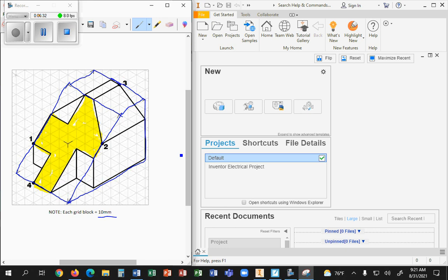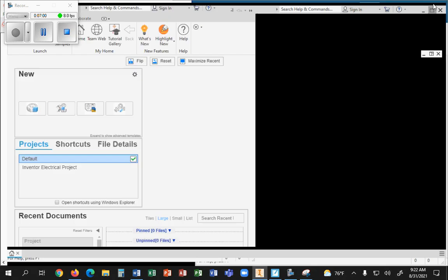And now moving over to Inventor. Okay? We needed to know the units of measurement. We know we're going to do the first angle projection because it's metric, but the first angle projection doesn't kick in until we're in detailed drawings. Remember that. So we're going to go to New. The first thing you're going to say is, why do you go to New? Why don't you just jump into New Part, right? That should be a question in your mind. Why am I telling you to do that?